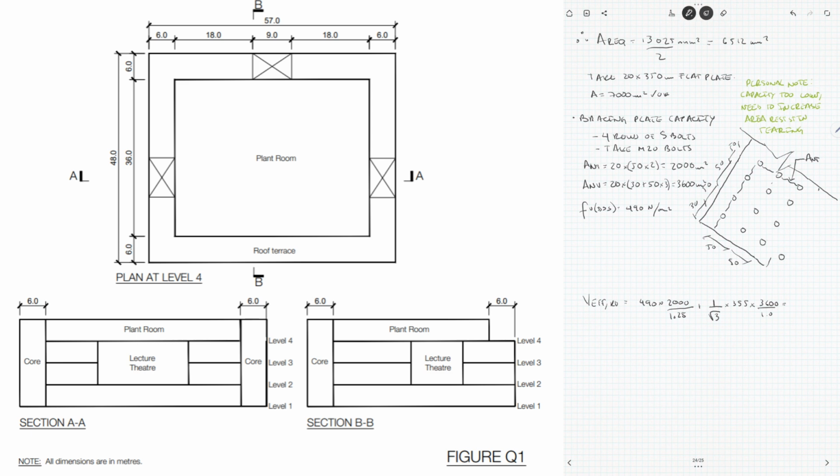And I found that tearing shows that, okay, I understand what the weakest point of my bracing is likely to be. The rest of the bracing will be stronger than this part of the plate. And tearing is a relatively simple calculation, and it's easy to templatize. You just need to work out the area that is going to be under tension, the area that is going to be under shear, and then you can work out the capacity for tearing.